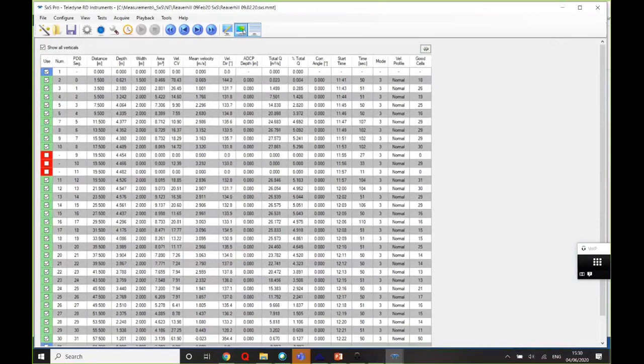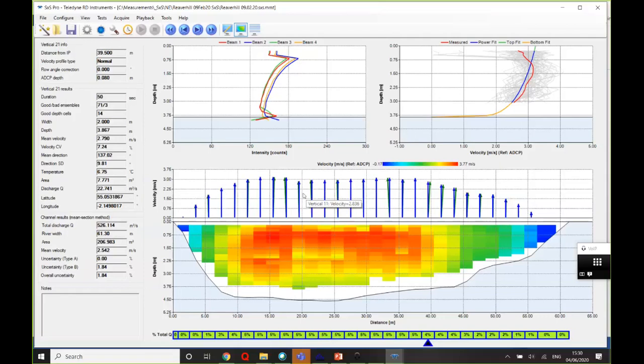Well, what I was going to suggest on this is something I learned from the French. With their surface velocity measurements, I don't know what they do with stationary ADCP measurements, but for that reason and a couple of others, they tend to do a vertical, then skip one, then another, then skip one, then another, then skip one. They do every other one, and then they fill in the gaps as they come back across. They do it so that in each crossing of the river, you've got enough data that if the batteries went flat or if something drastic happened, by the time you've got to the far bank, you've actually got a usable measurement, and then they improve that measurement if the conditions aren't changing too rapidly by infilling on their way back.